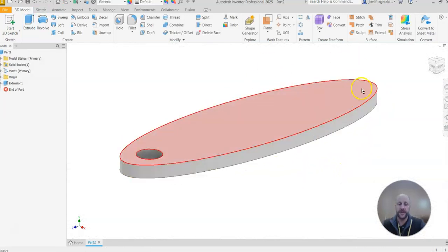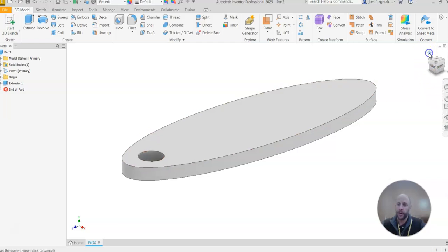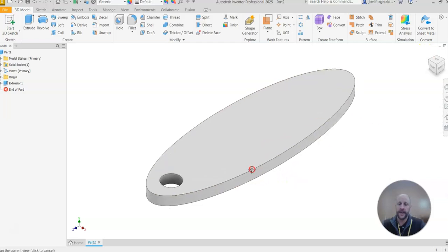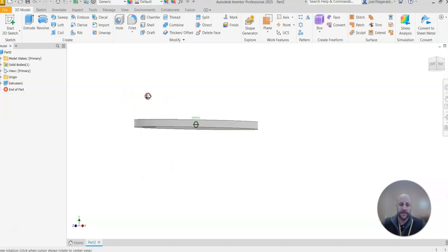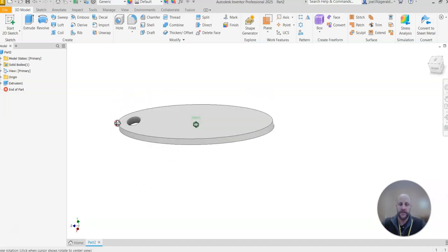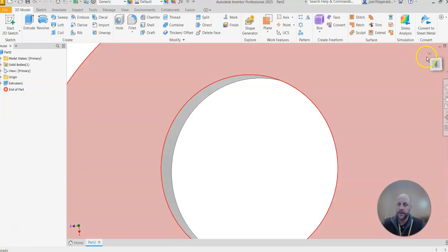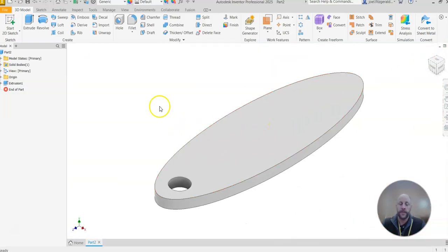Now, a few little things in Inventor here. If you want to rotate your view, there's usually a little home icon that allows you to rotate it back to square. Another shortcut, if you press the Shift key on the keyboard and press the middle mouse button, it's a little bit tricky, this one, you can rotate your view. And if something goes wrong, you can click back on here to bring it back into shape. Cool. All right, next step, we're going to do another sketch. We're going to cut out. This bit's a little bit trickier, but follow with me.